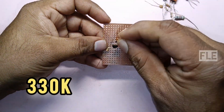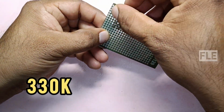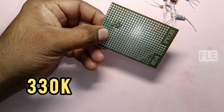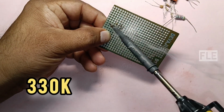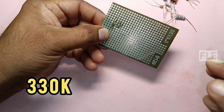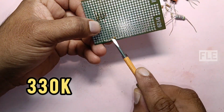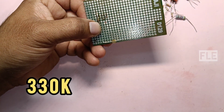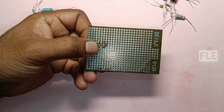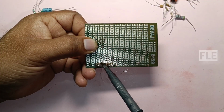Connect a 330K resistor between the base terminal and the positive terminal. The 330K resistor is connected between the positive terminal and the base terminal of the transistor. And this is the plus 12 volts terminal.